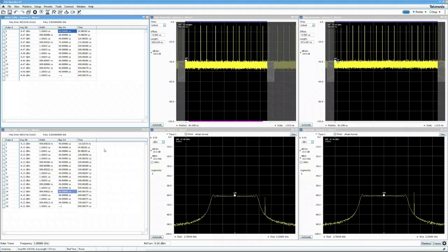Because we are applying the trigger on channel 1, it is the 0 position. It shows clearly that there is a 25 microsecond delay from channel 1 to channel 2. From the radar to the target simulator's output, there is a 25 microsecond delay. Let us analyze this delay in a more insightful way.